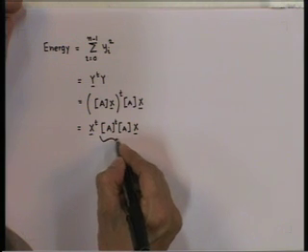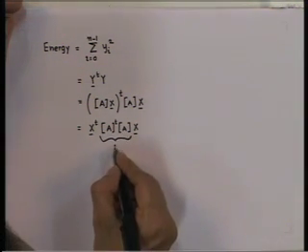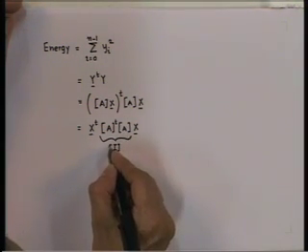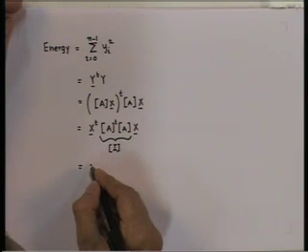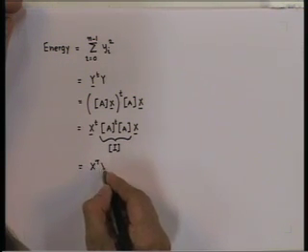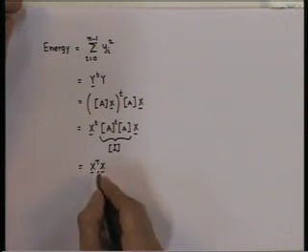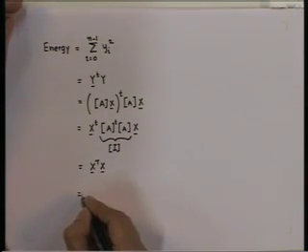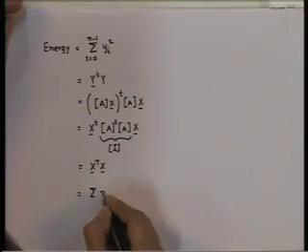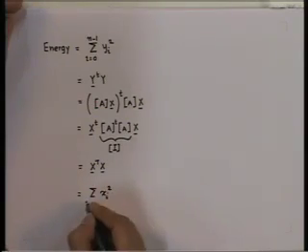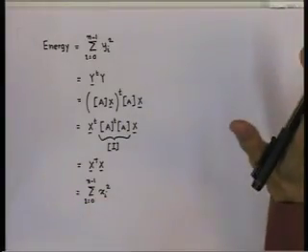Now, if we choose this to be an orthonormal matrix, then this is equal to x transpose x, the dot product of x with itself, which is equal to the energy in the source output vector. So, we choose the linear transform to be an orthonormal matrix because it preserves the energy.